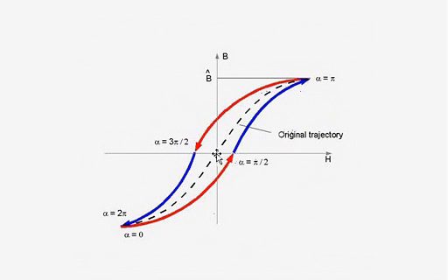There would be two ways to do that, and both ways would be valid, and I chose probably the simpler way, but maybe not the best way. One way would be to use two successive coupled QuickField solvers, one with the blue part of the BH curve or the hysteresis curve and one with the red part. I think it would be possible to do that, although I didn't try it.